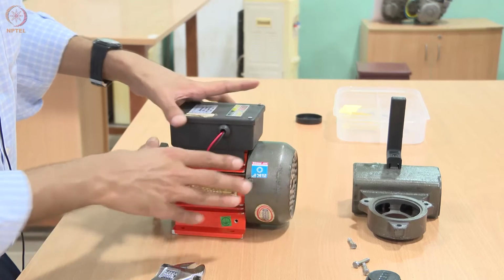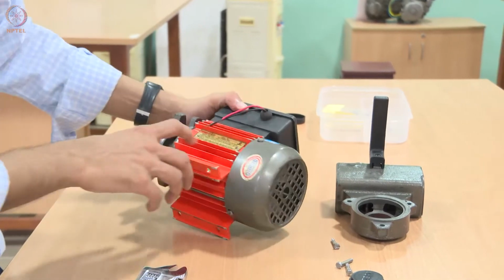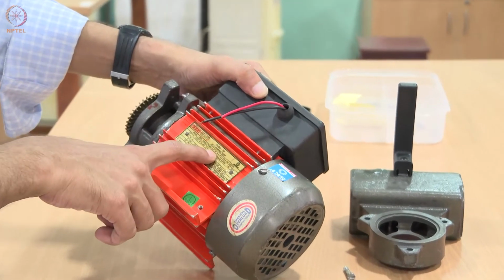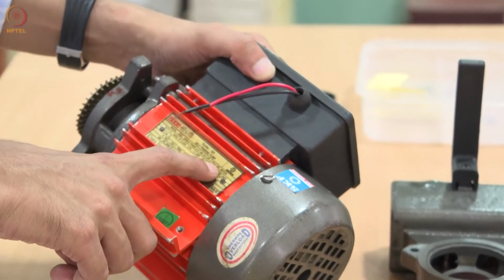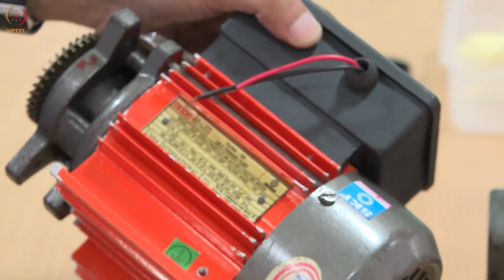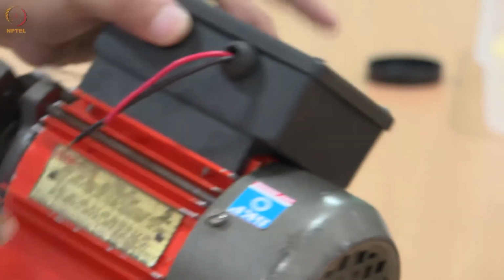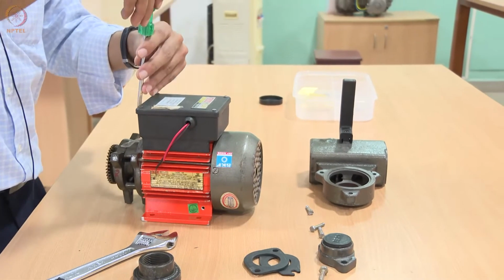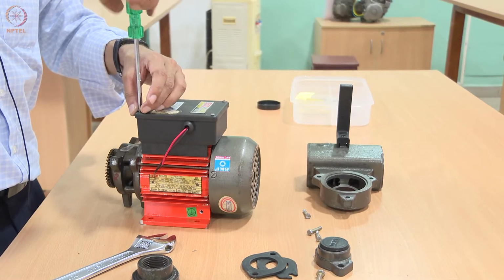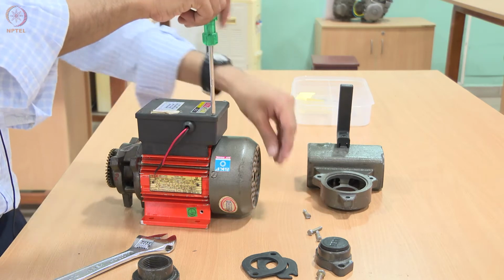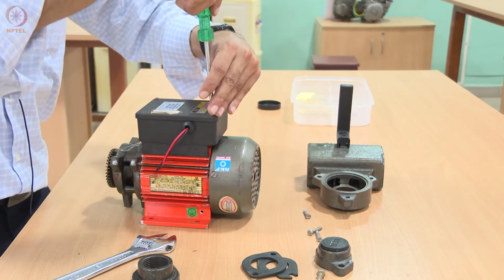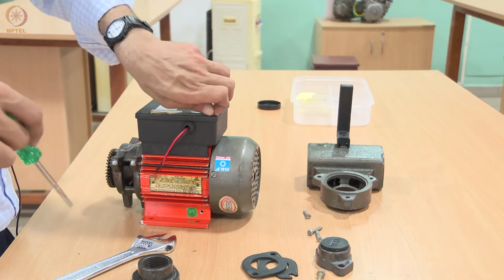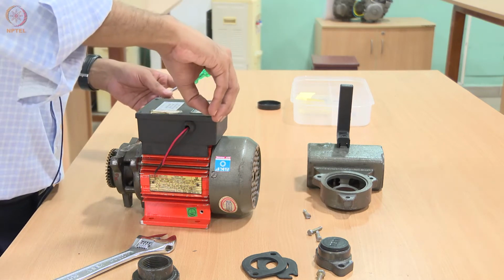So when you look at the motor, this is a standard one. Let us look at the nameplate. The nameplate says it's a single phase, 0.37 kilowatt, 2-pole rated motor. Why is there a 2-pole here? Because we know from the other study that no single phase motor is self-starting. You always have what is called a capacitor start and run motor. So basically you have two windings.